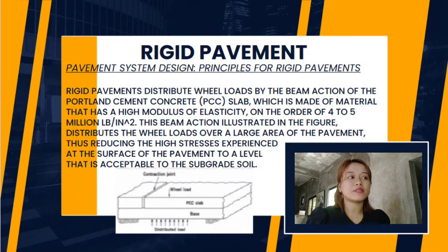The concrete slab itself supplies a major portion of a rigid pavement's structural capacity, while flexible pavement, inherently built with weaker and less stiff material, does not spread loads as well as concrete. So therefore, flexible pavements usually require more layers and greater thickness for optimally transmitting load to the subgrade.